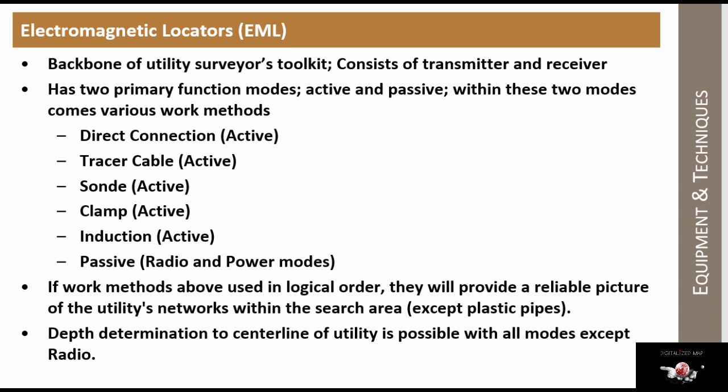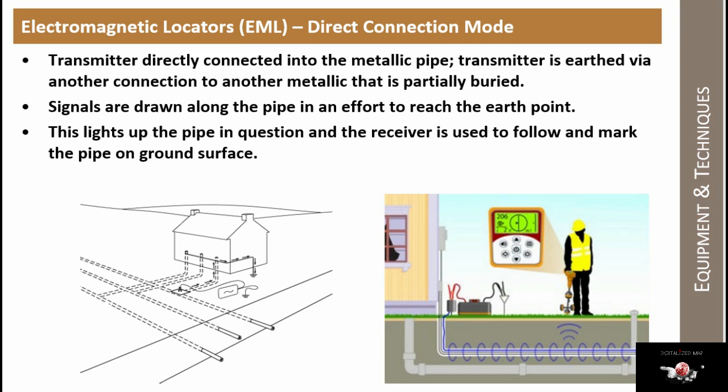If the work methods above are used in logical order, they will provide a reliable picture of the utilities networks within the search area, except plastic pipes. Depth determination to centerline of utility is possible with all modes except radio.